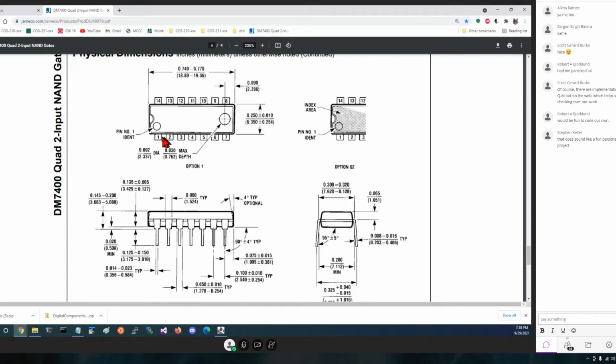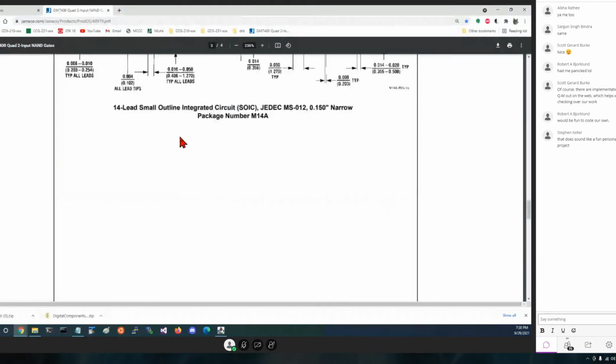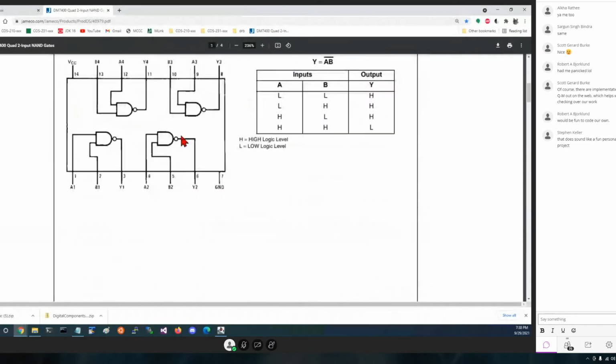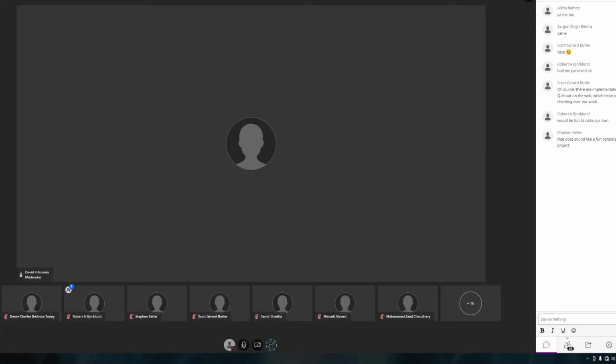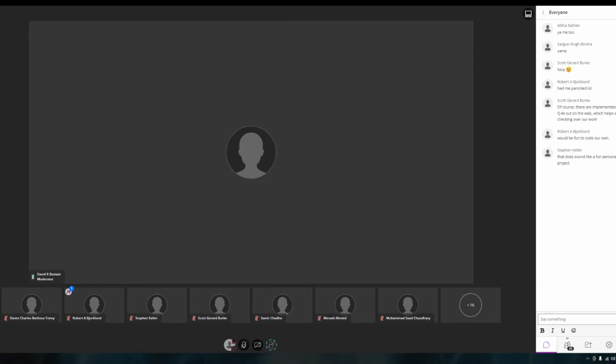That means that if I leave pins 1 and 2 not connected, pin 3 will do what? Well, we have to look at the truth table. If both of these are 1, what's pin 3 do? Pin 3 low for us if we left the inputs high. Not a good practice, but it can be done. So if somebody asks you about the binary on this, has more than 2 inputs, it does. It's got a 1, it's got a 0, and it has a not hooked up.